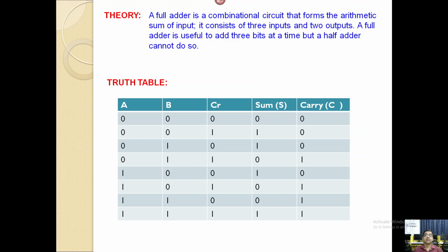Okay. As we already defined, if there are more than two bits, that means a 3 bit number, the full adder is required, and we will get the output as sum and carry. So the maximum input is 3: A, B, and carry C. 3 bits, 2 to the power 3 is 8, so 0 to 7 are the input values, and we will get the sum and carry.